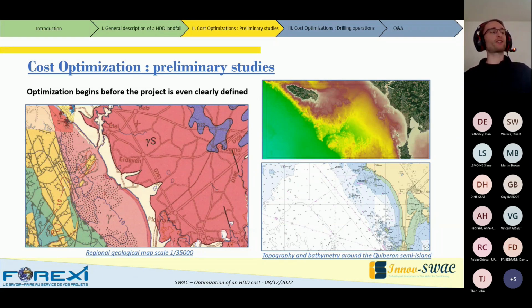I'm not going to stop there either. I'm also going to ask him to study the general climate of the area. I'm going to ask him about wind strength. What's the general direction of the wind? What's the average wave height? What's the expected length of the surf zone, which is where the waves are generated? Essentially, I want to know how far from the shore I will have to be to work with a calmer sea and allow me to pull back my pipe easily.